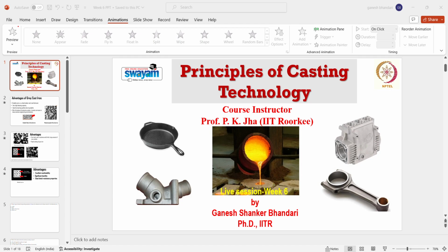Your mold is at a very high temperature and is not surrounded by anything, so it is in direct contact with air and is going to oxidize continuously. Oxidation and chip formation on the surface will be there, so you will get a casting yield of around 70 to 80% most probably. So that cannot be true. We cannot say that the casting yield is very high.